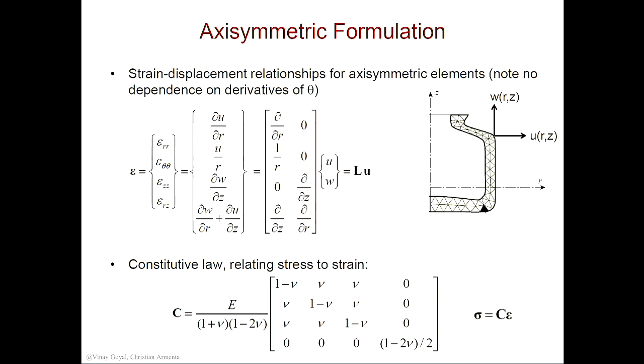And so, as usual, some tricks here, I can take the strain displacement relationships, which are given here, and I can put them in a form that I can use later on for finite element formulation. So if you took the first row, I call this the differential operator L, if I take the first row, multiply by this column, I get that equation, that relationship. If I take this row times that column, I get that relationship, and so forth. You can see that it works out very nicely. Okay, and so this is nice because I can keep everything in compact form. I can use it later on for my finite element formulation. Is that clear? So you'll be doing some of this for the subsequent homework, basically the final. I call it homework. It's an exam.